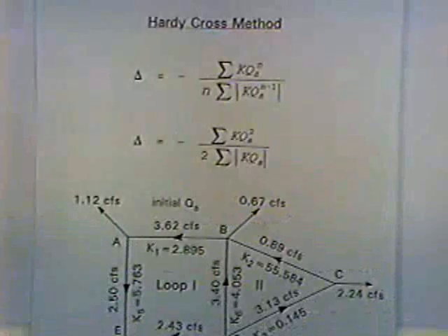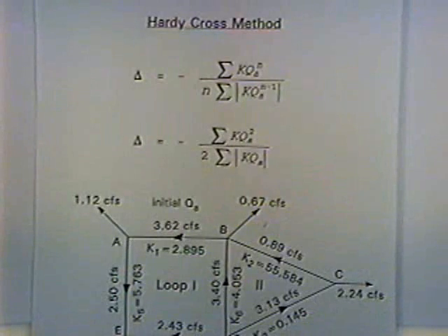So we've reproduced the Hardy-Cross basic equations on this sheet along with the network we're solving for. To get started, for example, in the KY pipe program that so many people use, the program automatically assumes 1 cubic foot per second in every pipe and starts from there.